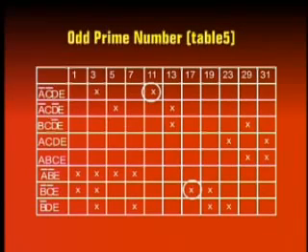Circles are marked in cells having X, which represent minterms covered by only a single prime implicant. Thus, the minterms 11 and 17 are covered by only the prime implicants A bar, C bar, D, E and B bar, C bar, E respectively. These implicants do not cover all the minterms. The other essential implicants that have minimum number of variables and which cover all the remaining minterms are B, C, D bar, E; A, C, D, E; and A bar, B bar, E.